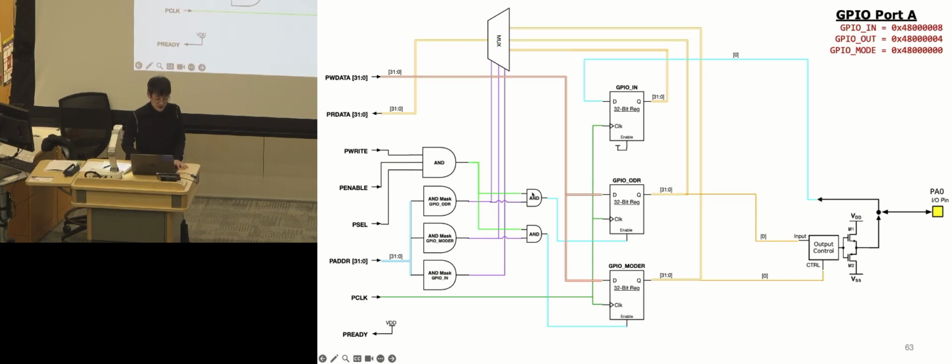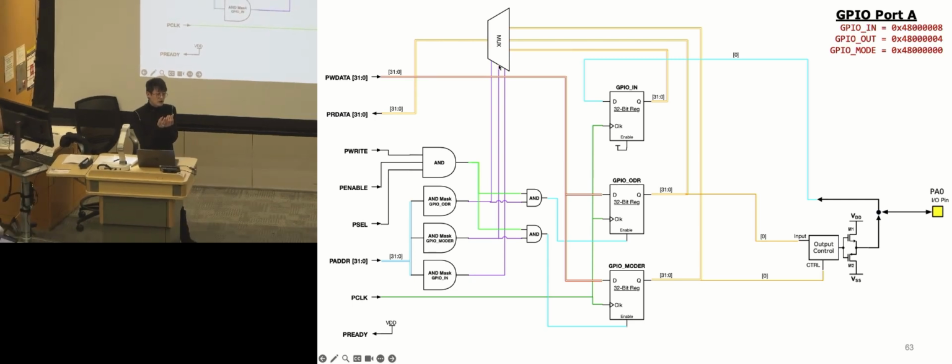That's a very good question. So technically in this one, the reason is, each output from this is 1 bit, 1 or 0, right? And then it goes here so that it only looks at the one that is 1, because they cannot both be on at the same time. So technically you only need 2 bits for this, but you will need additional logic gates here to handle that, because these 3 signals can only be on one at a time.